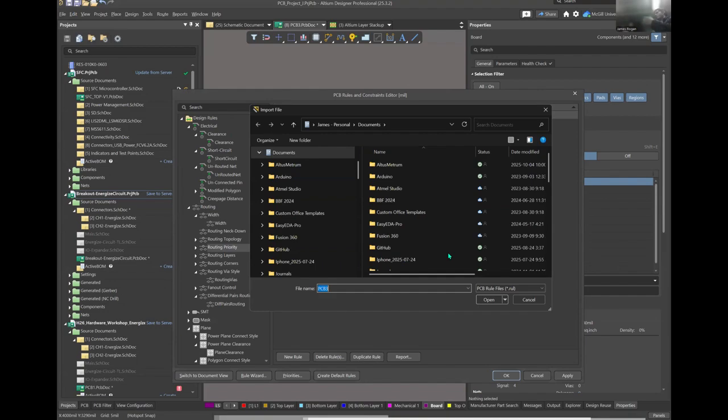This will actually configure all your design rules according to that .rul file. And if that person has gone through the JLC PCB manufacturing capabilities and put them in properly, then that design rule file will be quite useful for letting Altium know what's improper in your design.